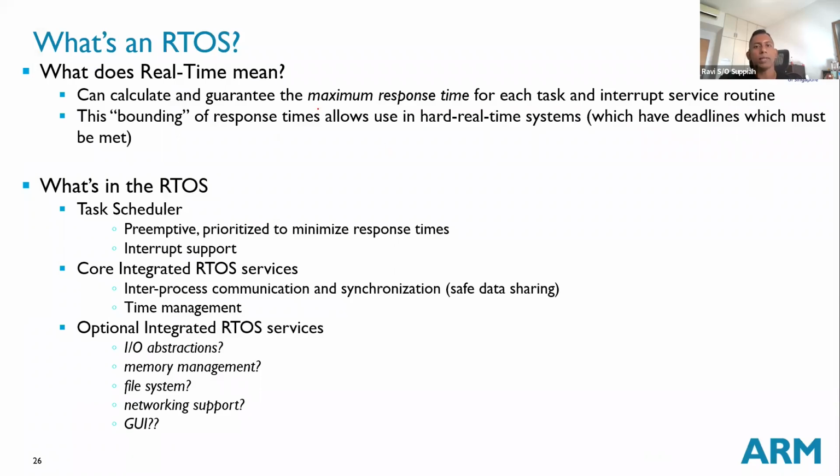So what we want is to have the fastest response time, given the requirements of the system. This involves many different things. The first thing is, of course, the scheduler. The scheduling policy is what we discussed just now, that means how do I manage a task to go from ready state to running to waiting or blocked and things like that. So there are different states that the OS needs to keep track of for every task that you introduce to the system.